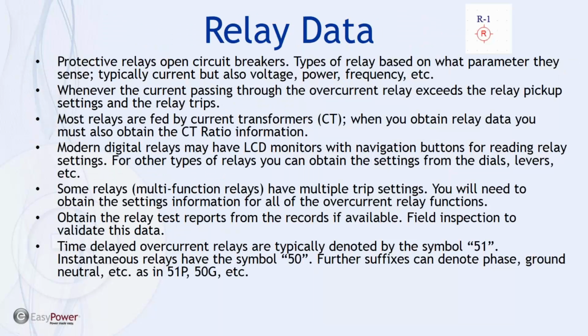And then, as important as anything else, the elements that control the time of the arc, that quench the arc, are highly important when it comes to calculating arc flash. Relays are an important element in this process, and so you need to record as accurately as possible the CT ratios that are feeding the relay. Obviously you want to have these on all three phases, or if you include ground and neutral, the multiple phases.